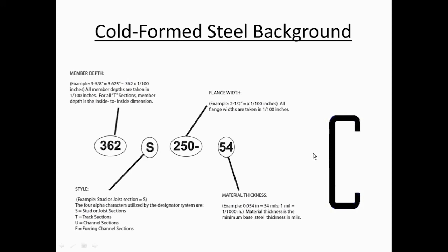One of the unique features of a cold-formed steel stud is its unsymmetric aspect, and by that I mean it's not symmetric around its key axis, which would be this one here, the vertical one. And what happens is when you load it, as I described before on the flange, it wants to rotate around a point right around in here, which is called the shear center.